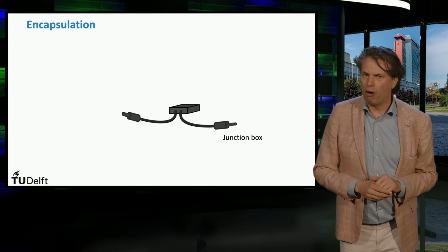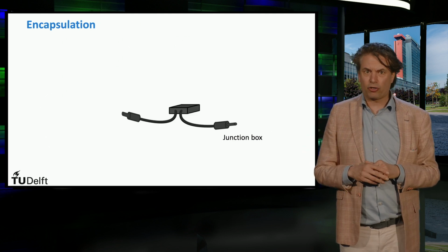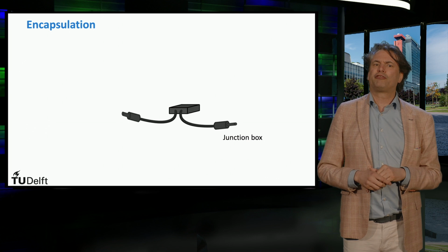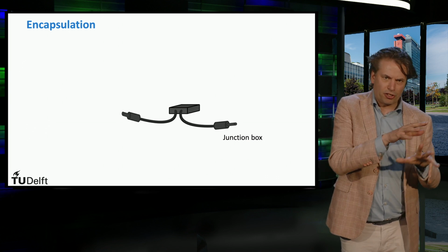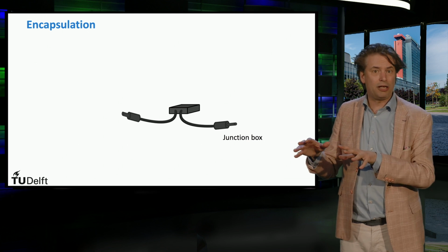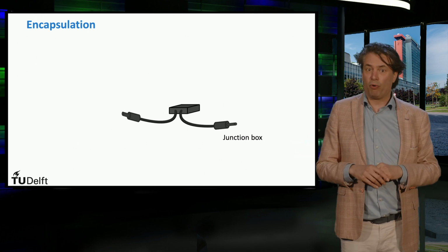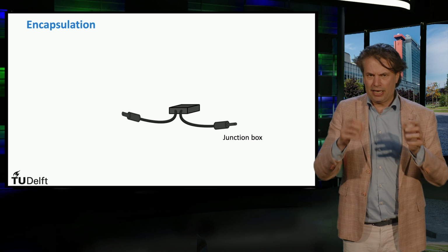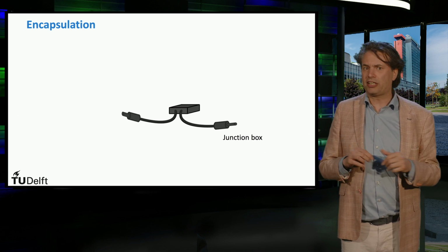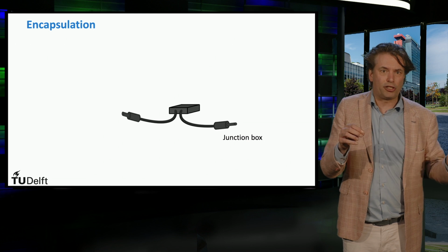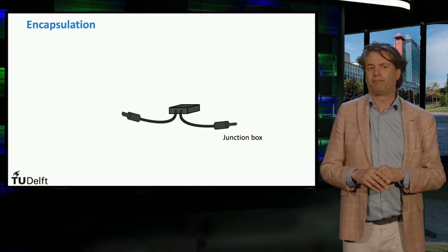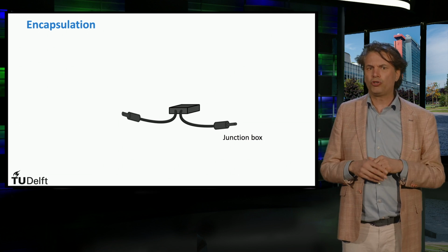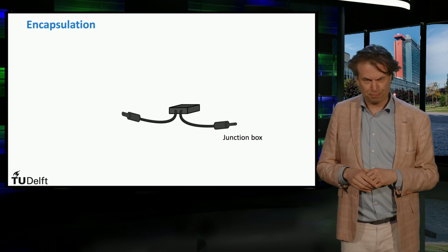The junction box is located underneath a plastic or glass backsheet at the back of the PV module. The junction box serves as the interface between the conducting contacts of the panel and the DC input and output cables. This plastic box is designed for outside operation and to withstand heat cycles. Inside the junction box we can find a switch that enables all the cells to be either connected in series or some cells in series and some rows in parallel. This way the output voltage and the current of the module can be modified. Usually it also contains some bypass diodes.